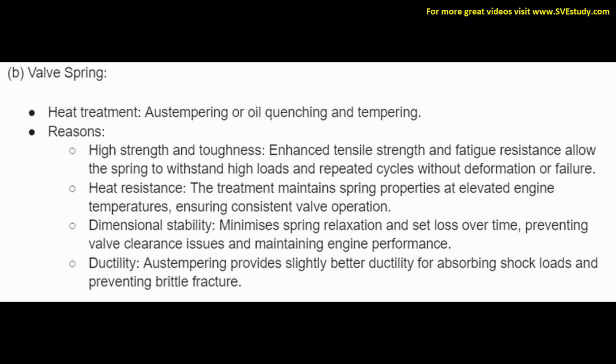B. Valve spring. Heat treatment: austempering or oil quenching and tempering. Reasons: high strength and toughness. Enhanced tensile strength and fatigue resistance allow the spring to withstand high loads and repeated cycles without deformation or failure.